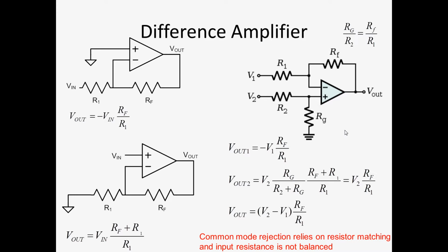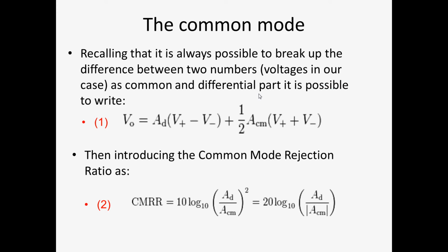But every time you have a reference, you connect your reference to the negative input of your amplifier, and you connect the electrodes of interest to the positive input of the amplifier, so that you always do my signal of interest minus the reference. Now, amplifiers could be good, manufactured fantastically well, but they aren't perfect.